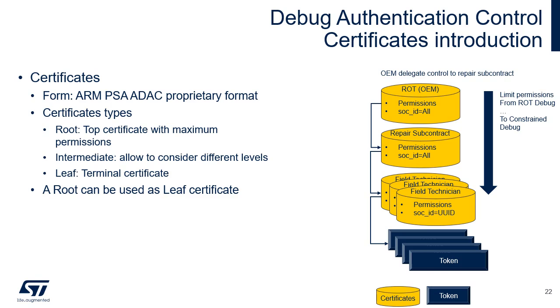The default mechanism for authentication relies on a challenge response protocol. The response to the challenge is a signed authentication token, also called the debug token. A chain of certificates links the key used to sign the authentication token to a set of one or more trusted anchors. Based on the vendor's needs, the chain can be of arbitrary length, ending in a key directly linked to a programmed root authority. Certificates allow a very limited provisioning, but offer a lot of flexibility. Different models to distribute the right to access different parts of the system can be implemented.